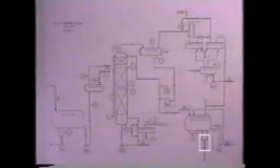Let's go back to the graphics board now and briefly review the steps we've covered so far. To begin the pre-startup checks, the outside operator checked to make sure the overhead product recovery tank drain was closed. Then he selected the recirculating pump to be used by first lining up the valves and then checking to make sure the pump operated properly.